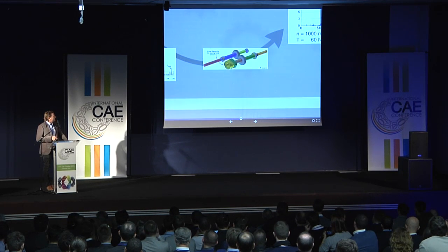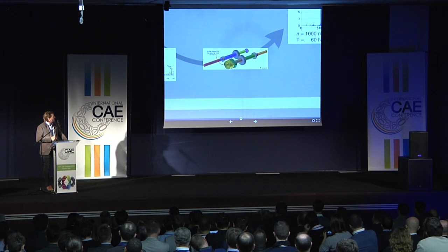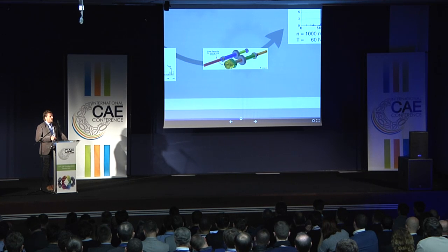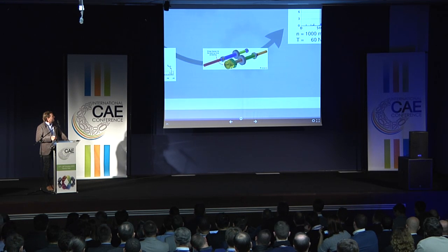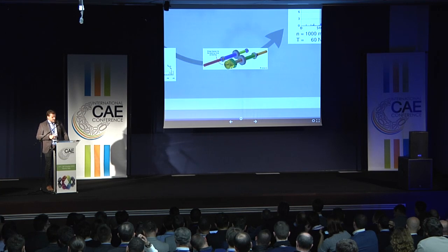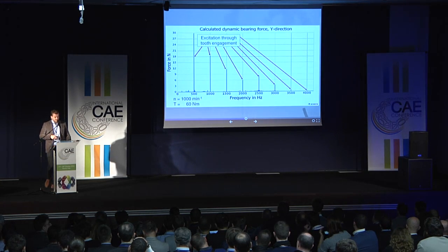Okay, so this is again the powertrain which we designed, just one gearbox section, 4 bearing positions, and this yellow and green block here is a block of steel, 2 blocks of steel, which is the bearing force measurement device. I'm going to tell you a little later what this is and how this works, but this is what I want to tell you: we're going to simulate this too. And with this virtual sensor, we calculate the dynamic bearing forces right at this point here. And the dynamic bearing forces look like this.